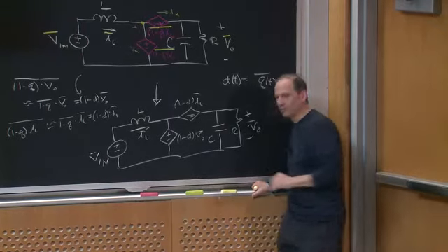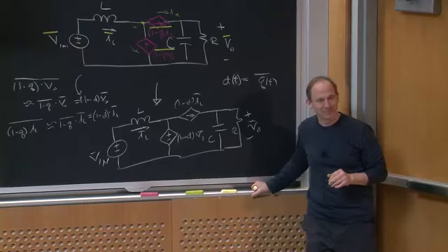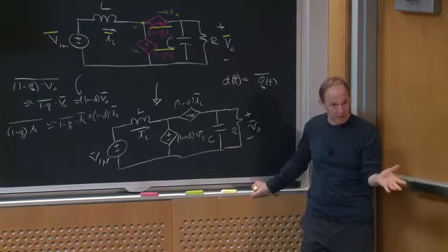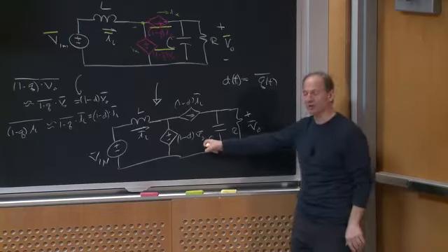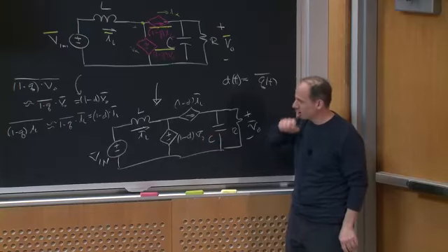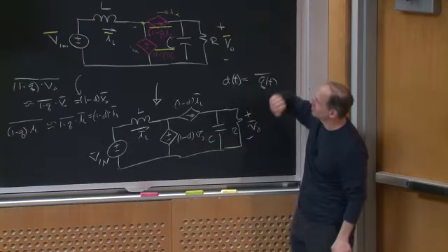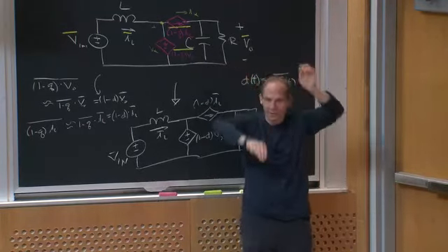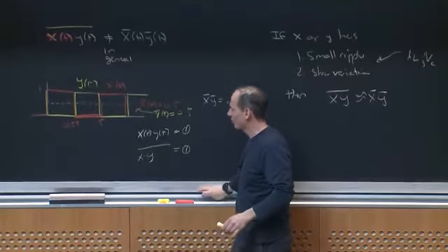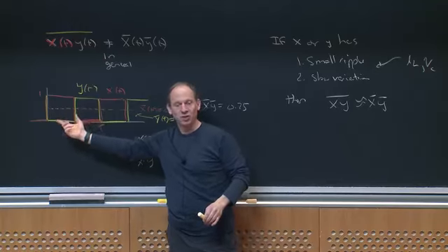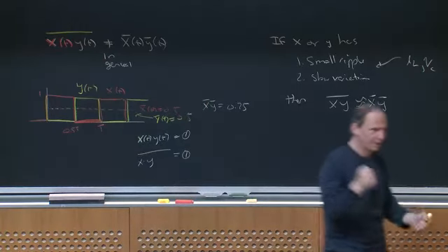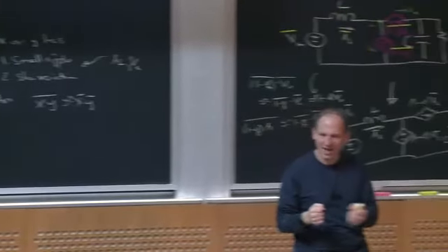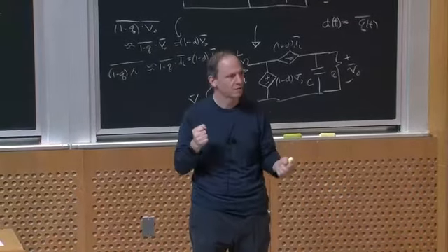It's very good for doing low frequency controller modeling. Okay, it's not useful for other things. For example, if I asked you to calculate power dissipation of components, you cannot use this model. Why? Because what would the power dissipation in the switch be? It would be the switch voltage times the switch current, both of which are pulsing up and down together. It violates this assumption I was talking about, right? In fact, the voltage and current on the switch actually look a lot like that. So I can use this average model to do things like control dynamics. That's perfect for it. I can't use it to answer questions like dissipation or other kinds of things.